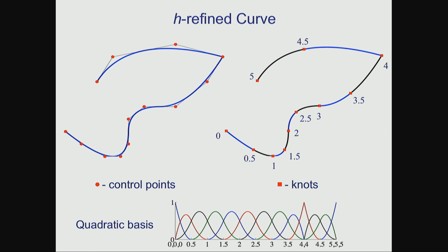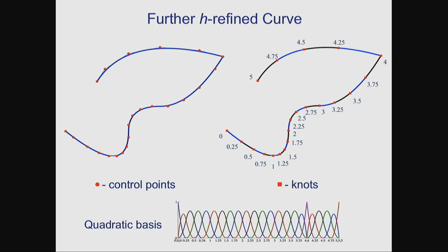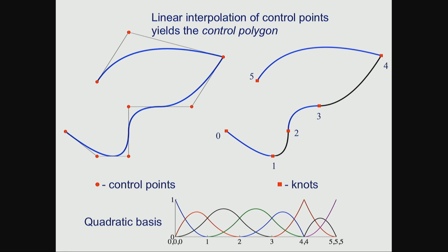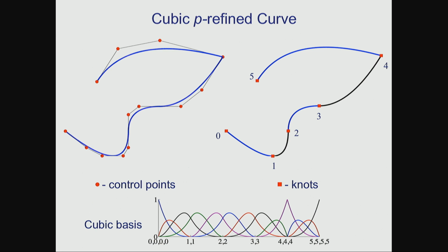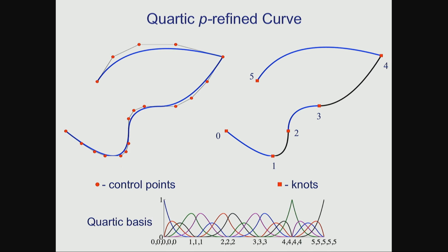You can refine simply by introducing knots, as you see here. Now, the interesting thing about refinement here is that the geometry and the parameterization do not change during refinement. You don't have to search for the geometry to do a refinement that respects the geometry. You have, from the get-go, the exact geometry. And you're embedded in it when you refine or de-refine. And you can take this further and further to your heart's content. You can start all over and do p-refinement, keep the continuity the same, but introduce higher order basis functions. Now we have cubics, now we have quartics, et cetera, with the same mesh.